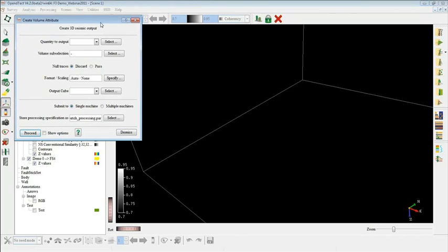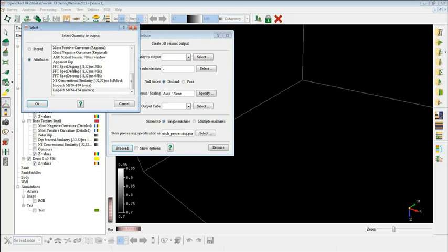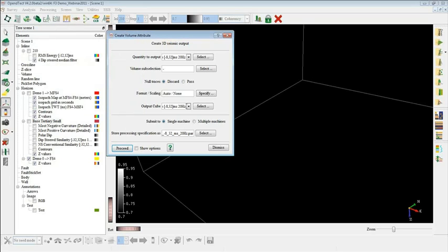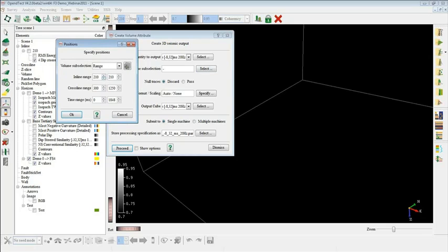At this moment, I'm going to select spectral decomposition so that we will see the multi-component outputs. You select this one, you press OK, and simply you can run it on a section. To do things quickly, I'm going to run it on one section only, so that I can demonstrate that one.